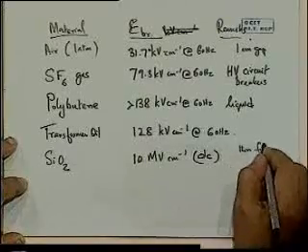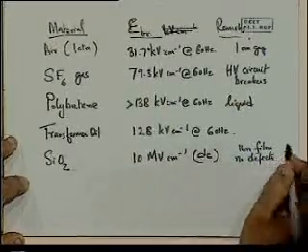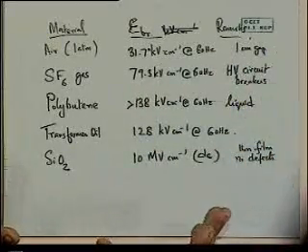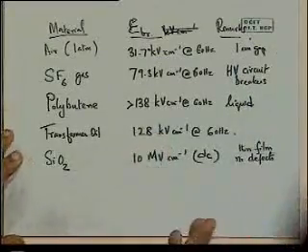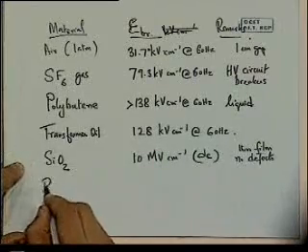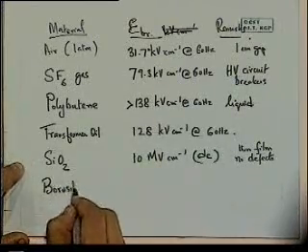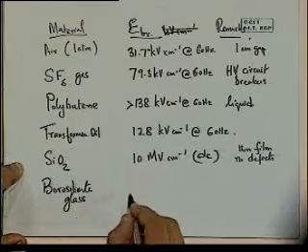But the assumption here is that first of all we're talking of a rather thin film and no defects. So your actual MOS oxide film may actually sustain lower voltages. This is sort of the upper limit, assuming there's no defects and it's a nice thin, smooth film. One final one, say borosilicate glass. I'm giving these so you can get a feel for the range of properties of different kinds.